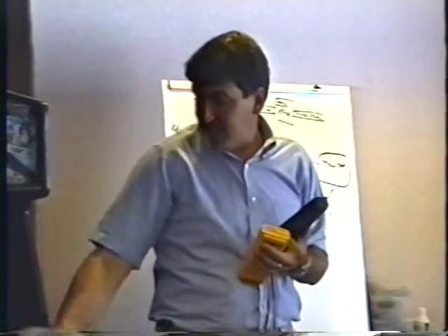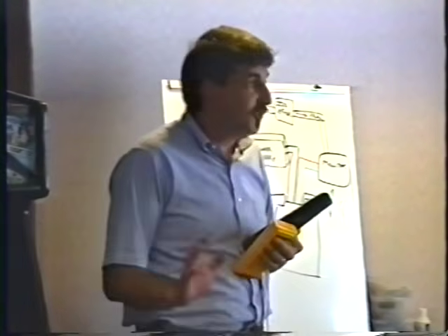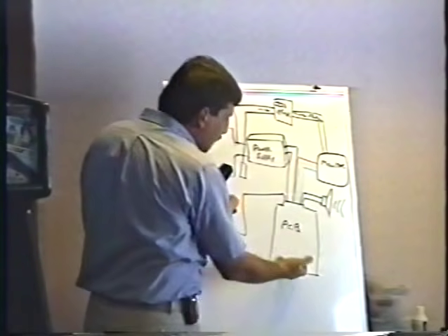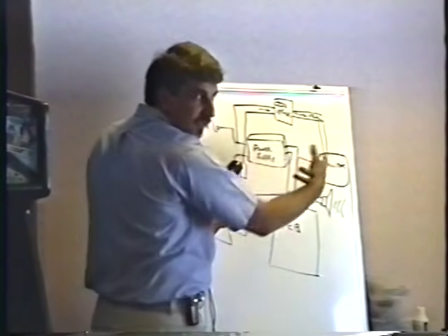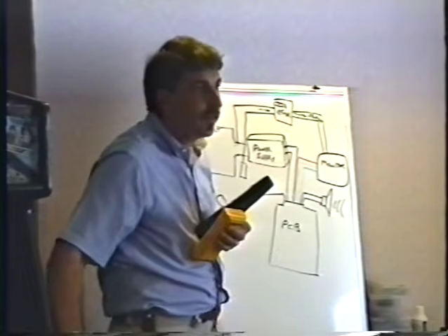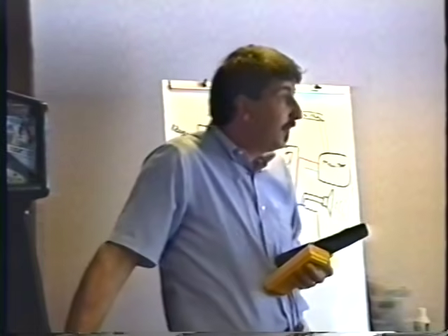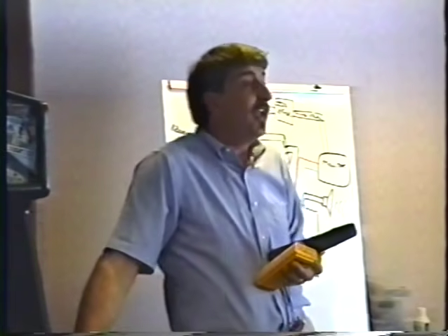The reason the monitor isn't showing anything is that the power supply is not powering the computer, so it's not putting out those red, green, and blue signals that go to the monitor, and that's why you're not seeing anything on the screen. Wouldn't it be really stupid to rip the monitor out and start working on that when there's nothing wrong with it?